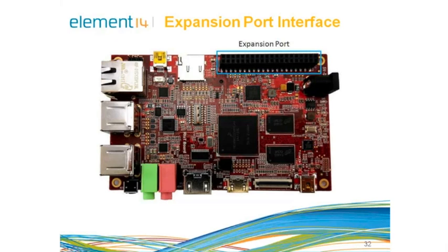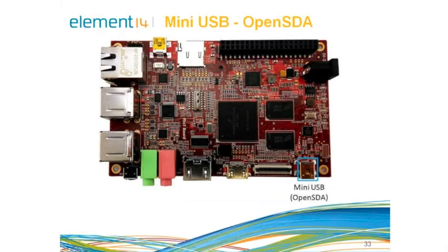It has an OpenSDA interface on a mini USB connector, as we can see here on the image. Now this OpenSDA is a low-cost debug and programming interface embedded in most of the Freescale boards. It handles debug communication between the PC and target via USB technology.